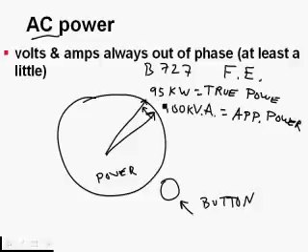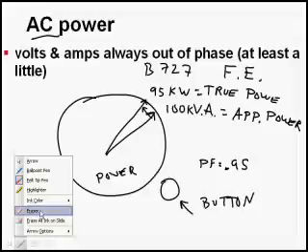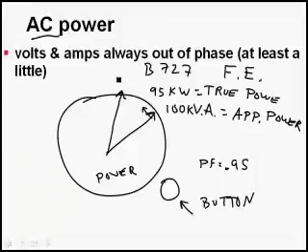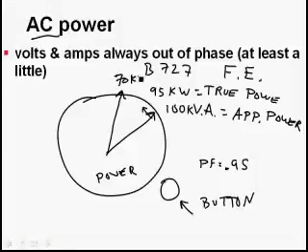And what you want is this 5% difference. If there's a 5% difference, that means you have a power factor of 0.95, and that's pretty normal. Let's say you're flying along and you push the button in, and instead of seeing it go down a little bit, you see it come down here to 70 kilowatts of true power. Wow, that means you have a power factor of not 0.95 anymore. You have a power factor of 0.7. The circuit is only 70% efficient, and something's causing it.